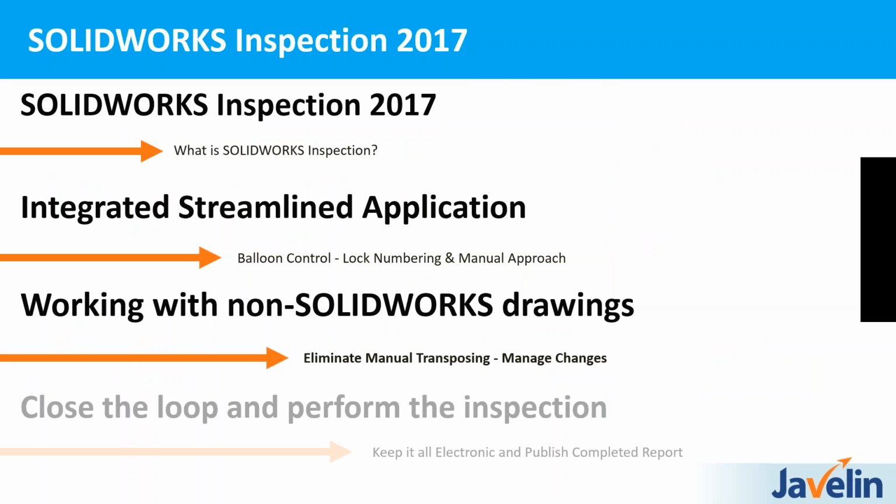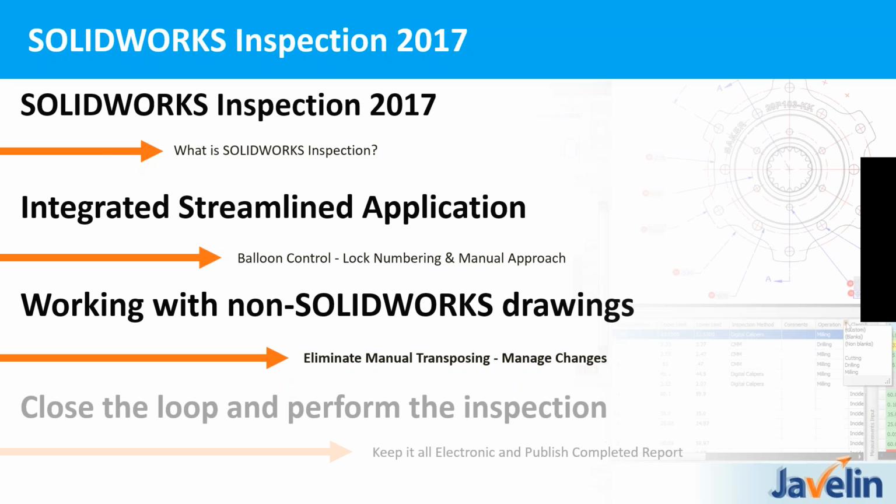So next, let's take a look at working with non-SOLIDWORKS drawings. And so that means, whether you don't have SOLIDWORKS or you're working with other file formats. Maybe you have a customer or someone that's using other CAD file formats, and you get a PDF or a TIFF of their drawing. We can go ahead and open that within the Inspection Standalone.